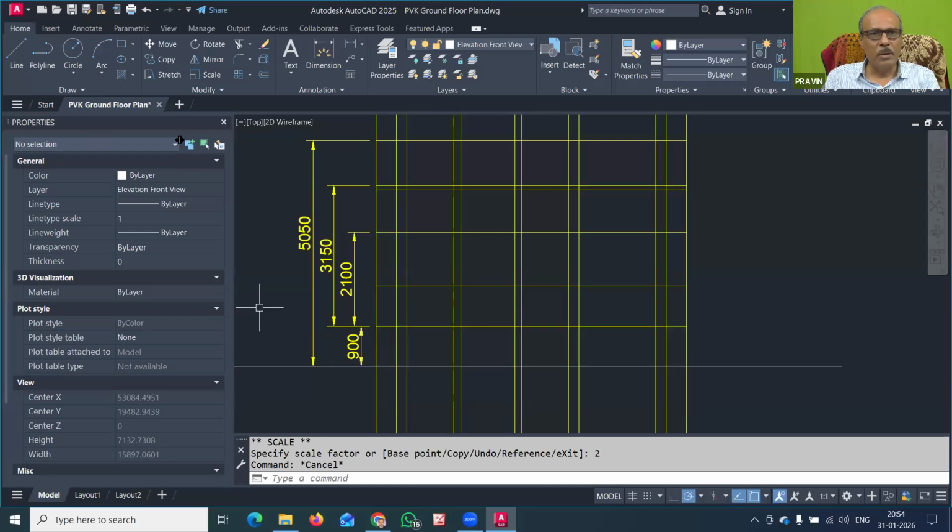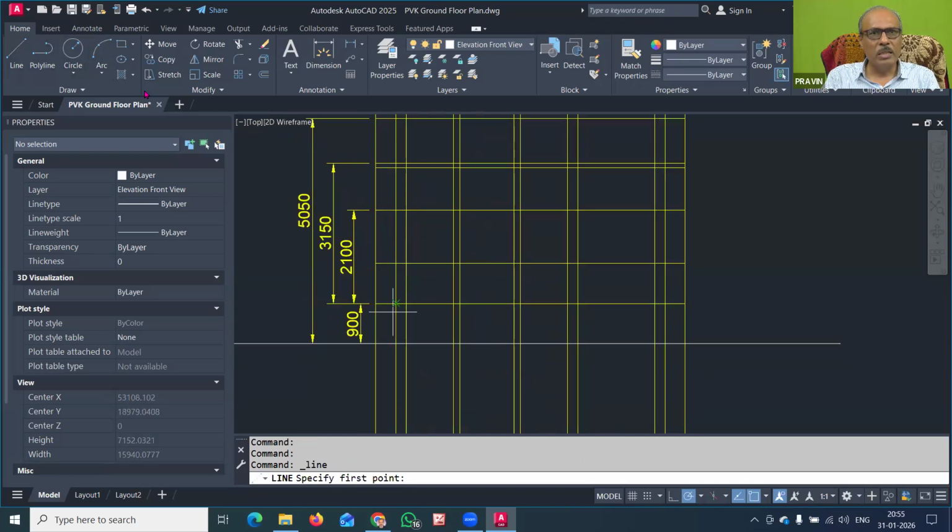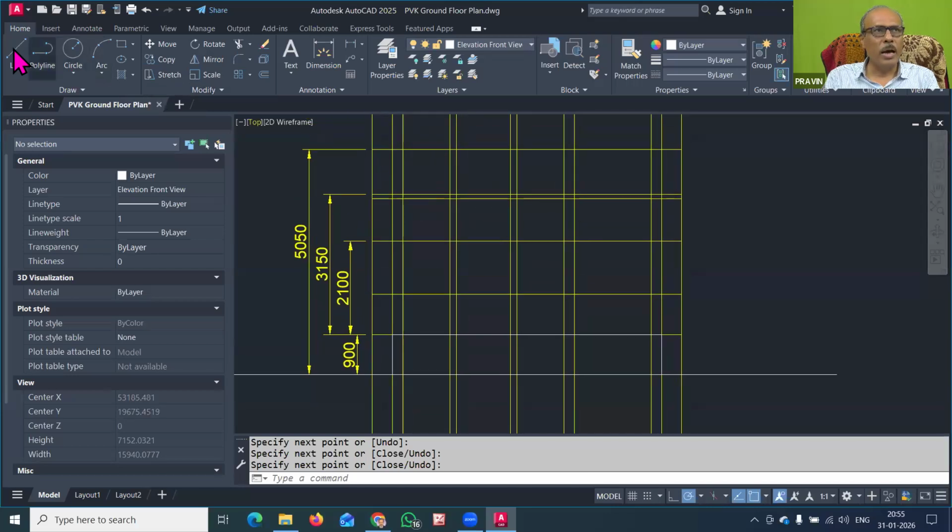It is very simple, you have to check from the building plan. So plinth height is from this point to this point. So there you can draw a line, indicating that from this point to this point, up to this point, this is our plinth. So now this was done. After that, there is a wall and then there is a slab. So here you can use again the line command. From this line to this line and up to this, the top parapet I can show and I can take this down. So this was done.